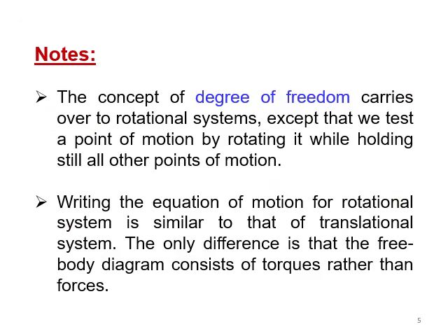Consider these notes before we start the rotational mechanical system modeling. The concept of degree of freedom is exactly the same as in translational mechanical system, except here the elements are going to be rotating, not moving in a translational way. And the way of writing the equations, whatever I taught earlier, will be very similar in rotational mechanical system, except I will keep in mind that the input in rotational mechanical system is torque and the output is the rotation theta.